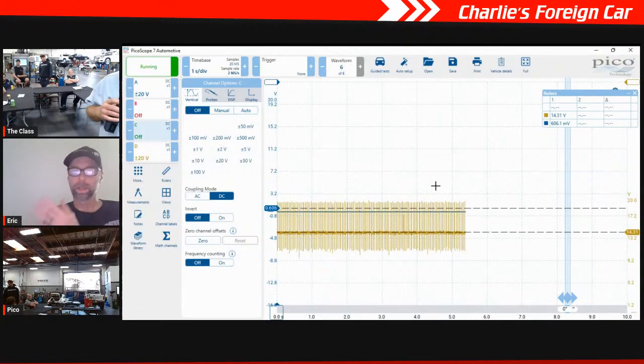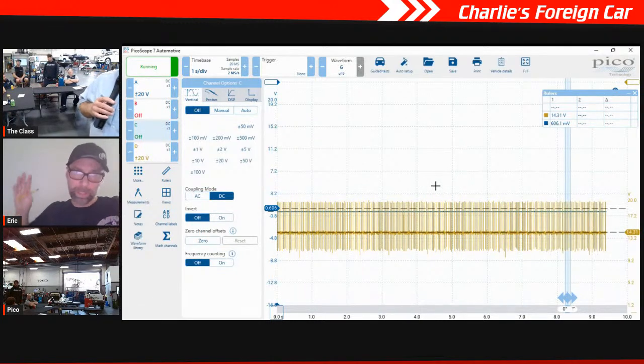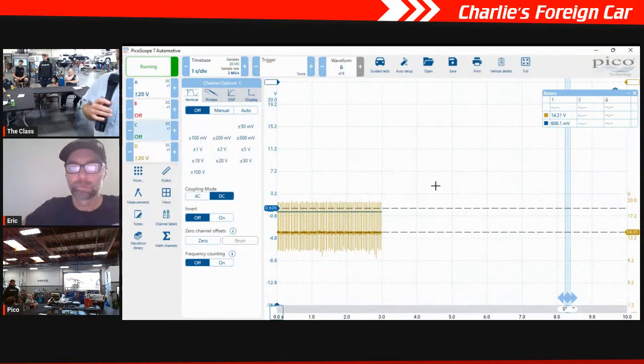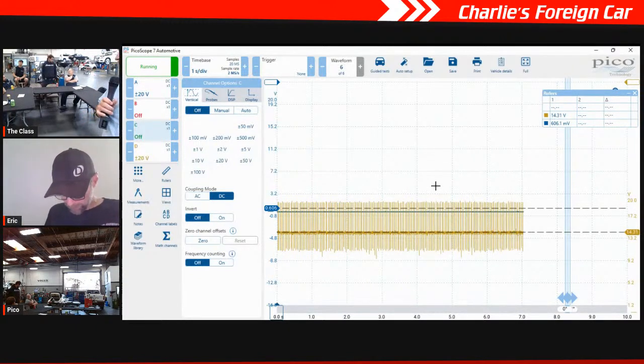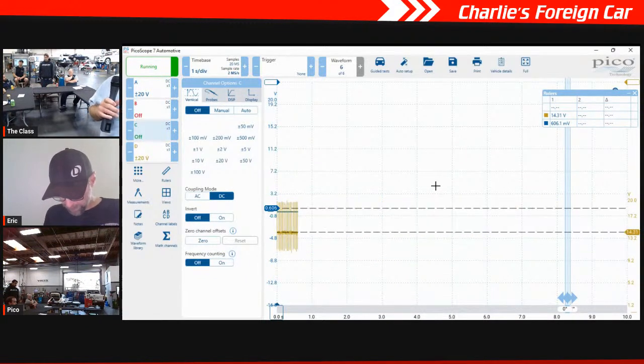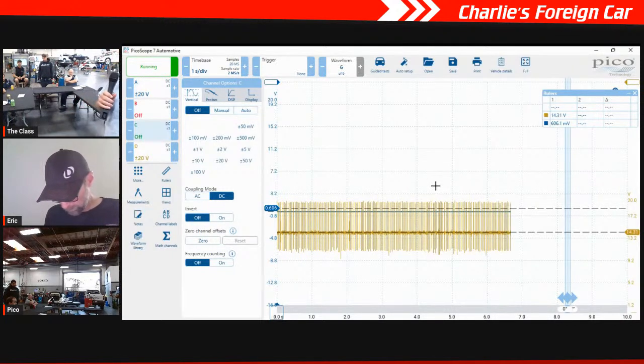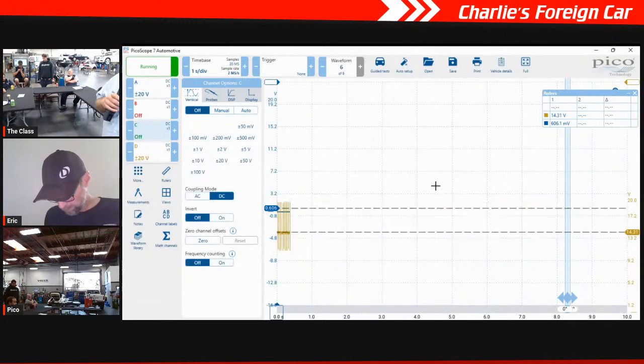Okay, I think that's key right there. So the control side is telling it to do something and zero is happening. Correct. Then we looked at it with the infrared, and it was 40 degrees cooler than the intake. So like no hot oil was flowing through it.